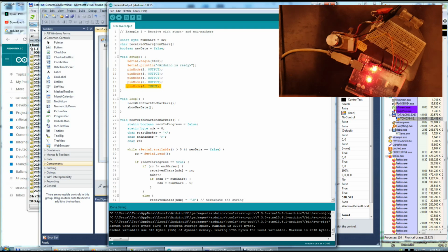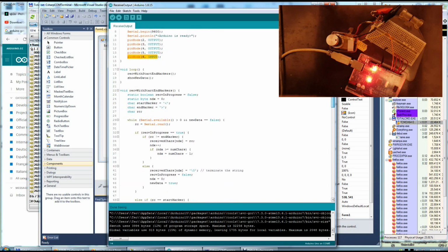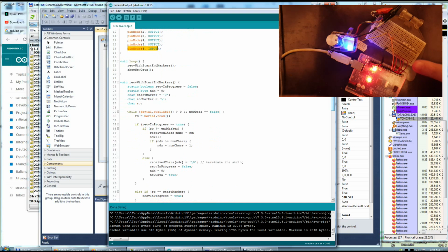You can probably see in the video that flashing. That is an oscillator that I have had for a very long time, made with a 555, and it has a knob, and I can change the frequency, how fast it can blip. The input from that oscillator is exactly on this pin 6 that you are seeing here. A yellow wire from it is coming there.